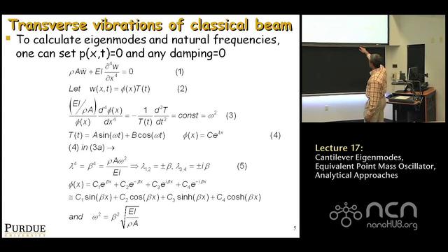So it's basically equivalent to writing that phi of x is written in terms of sines and cosine hyperbolics of beta times x, beta involving the natural frequency omega, okay? So we are at this point, and this whole analysis is now going to tell us what are the different omegas and what are the different shapes of the corresponding eigenmodes, okay? How do we do that?